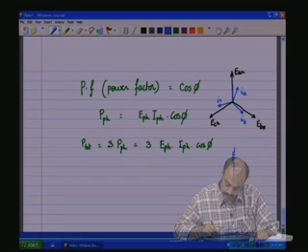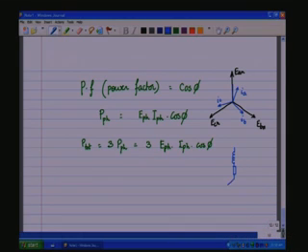How does this come about? You will see that if you have a circuit something like that, as shown here, this is A, B and C. This is inductive in nature, an RL circuit, R, L, R, L, R and L, same R's and L's, a balanced load. So, you will see the currents lagging the voltage in every phase.